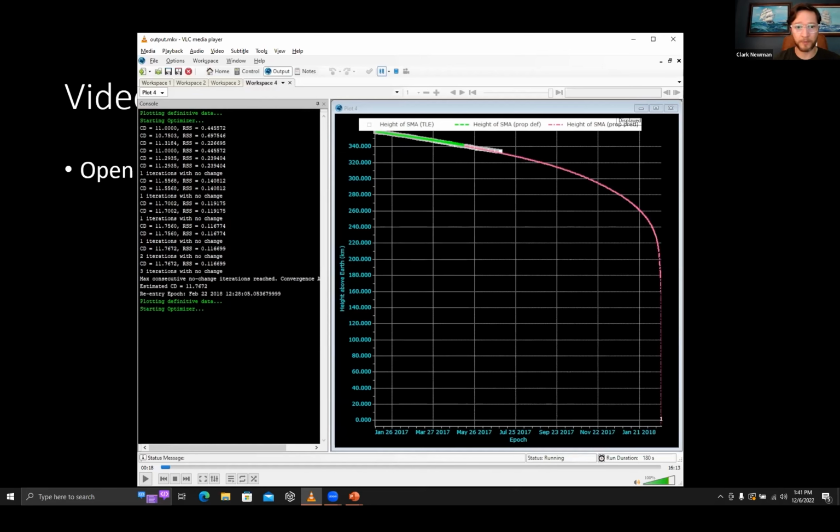So to add a little bit more context to this, the specific spacecraft that this is looking at is the Tiangong-1 Chinese space station, which did an uncontrolled reentry and actually re-entered in early April 2018. And so this just did a curve fit over a span of about 300 TLEs towards the end of its life. And so the next thing that this optimizer routine does is shift that window forward by 100 TLEs. So now we're looking at TLEs 100 through 400 of the set.